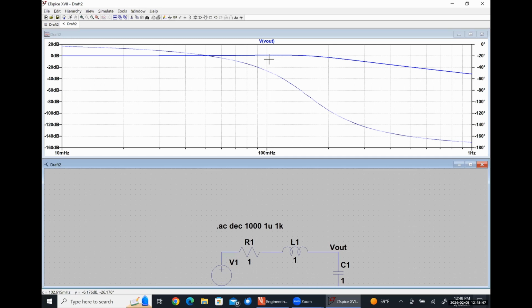but in this region, so like notice over here, it's nice and flat. And then we actually see a small increase. It's not huge, maybe half a decibel or so, probably. We can find out in just a moment. But there is a slight increase before it starts to roll off. That's actually why the cutoff frequency has that big, terribly long equation, because the cutoff frequency is 3 decibels from the maximum value. Our maximum value is no longer just 1. So near resonance, we are going to see that little blurb where it gets a little bit higher.